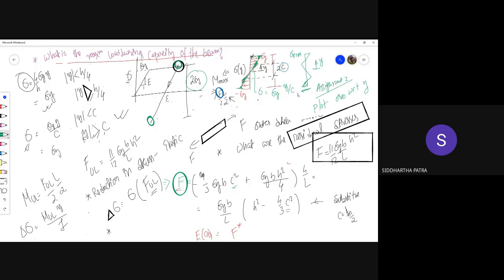It is like the opposite of a head start. It is set a little on the compressive side. So when it is loaded in tension, to reach any positive tensile stress value, it has to first overcome that compressive zone. So that actually helps the structure against failure. Okay, so that's the idea behind the residual stress.